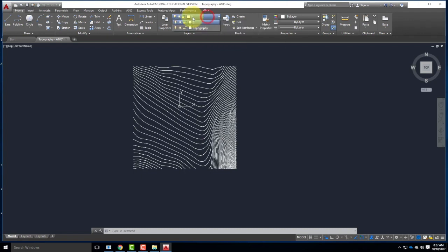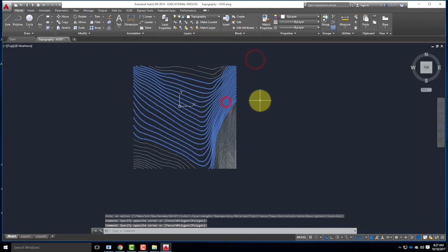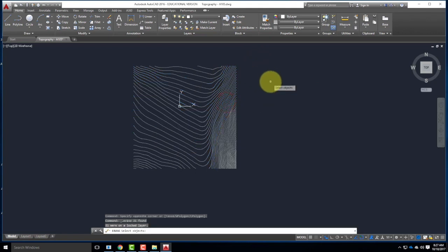Once you're switched to 0, look at the topography layer and you see that little lock icon, that little padlock. If you click on that padlock on the topography layer, it will lock so that you can't delete or move them. You can actually select them, but you can't delete them or move them or anything. And as you're drawing over the top of it, that's useful. Once again, I made sure that I'm on layer 0 and that topography has the padlock covered. We will talk at length about layers and what you can do with layers, but it's not something you have to worry about yet. We're only drawing the floor plan. We'll get to layers as you go forward from here.